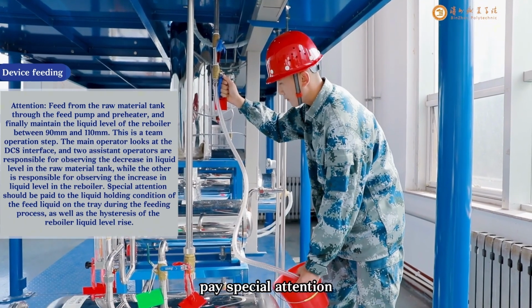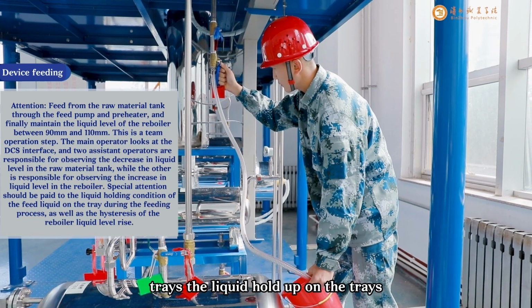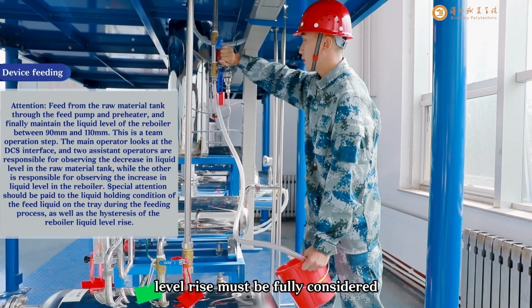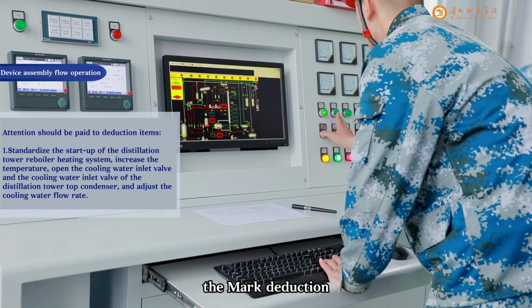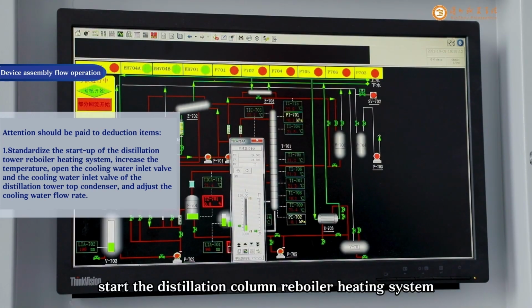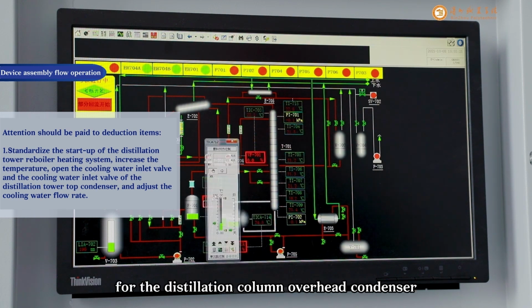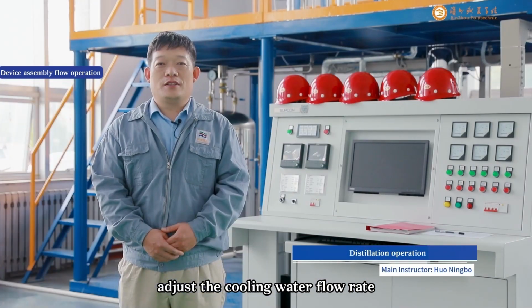Pay special attention, because the feed process passes through the column trays. The liquid holdup on the trays and the lag in the reboiler level rise must be fully considered. Points needing attention in this part are the marked deduction items. 1. Start the distillation column reboiler heating system standardly to raise the temperature. Open the main cooling water supply valve and the cooling water inlet valve for the distillation column overhead condenser. Adjust the cooling water flow rate.